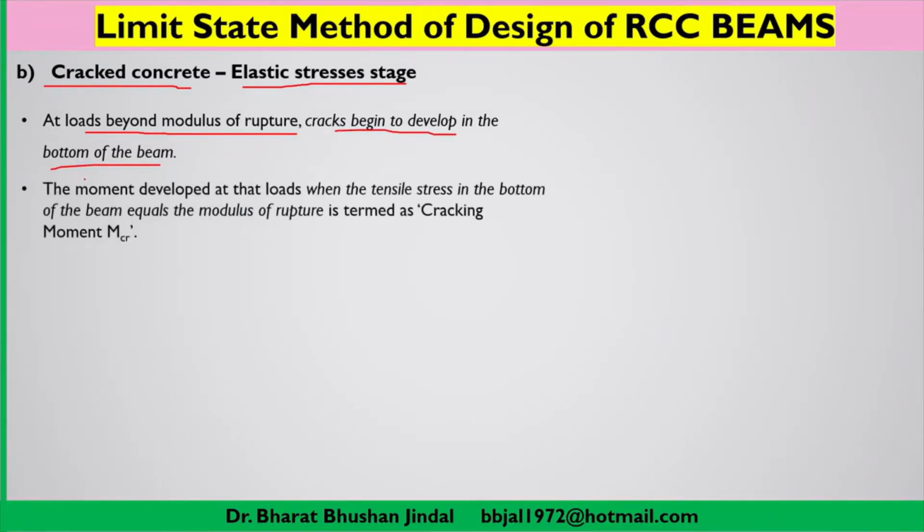The moment developed at these loads is the moment at which the tensile stress in the bottom of the beam equals the modulus of rupture. That moment, at the level of the modulus of rupture, is termed the cracking moment, M_cr.